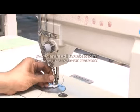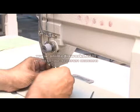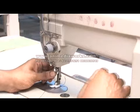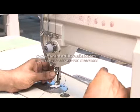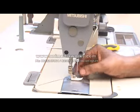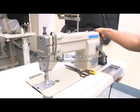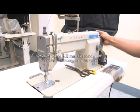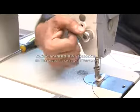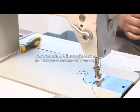Install the needle in the needle bar. Needles have a flat side and can only go one way. Insert the needle all the way into the bar and tighten screws securely. If the machine already has a needle, check that it is straight, sharp and securely inserted. To thread the machine, take the needle to the highest point using the hand wheel. Raise the pressure foot.